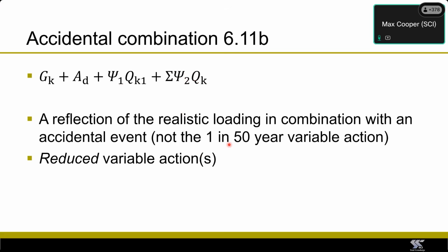This represents the fact that in the accidental load combination load case, we want the structure to stand up, of course, but this is not a regular event. Therefore, we don't expect perhaps the additional margins of safety on, for example, the permanent loads. And again, it reflects the probability that in this accidental design scenario, would we expect to have the full occupancy, whatever it might be? Probably not, and therefore this accidental load combination permits you to take that reduction.